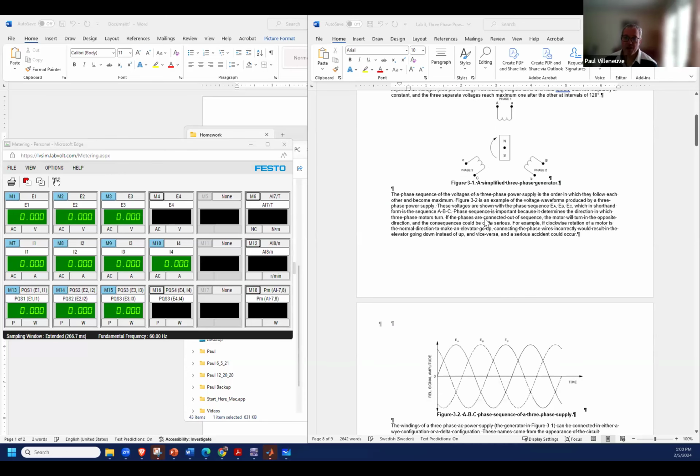And the other thing is we want to make sure that we have a three-phase system, which is going to allow us to have a potential difference between phase A, B, and C. All those should have a potential difference. Now, if they were all exactly in phase with each other, then EA and EB and EC would all be on top of each other. Well, how do you get a potential difference? Because at any moment in time, I see that EA has a difference in potential with both EB and EC, right? A potential difference is just measuring the difference between two voltages. So this minus this, you can see, is going to be a delta voltage there.